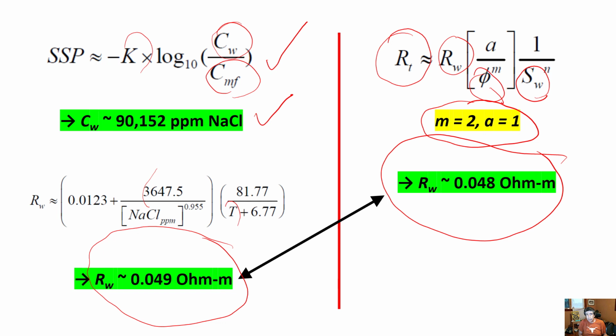This is what the SP calculation can tell us, that based on the assumptions that we have a normal condition sandstone, that we can truly assume that that sandstone for that minimum value of gamma ray log that we took can be assumed clean, and that gives us a very good comparison with the RW.